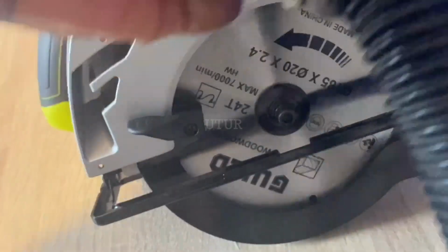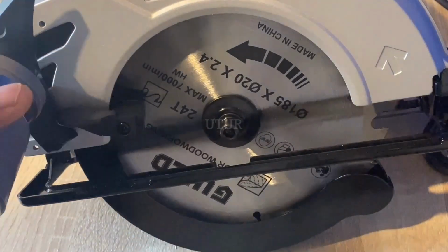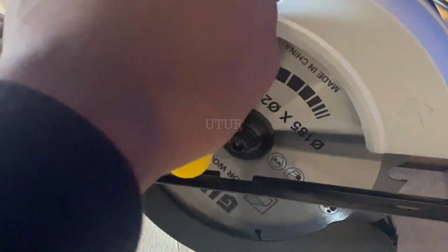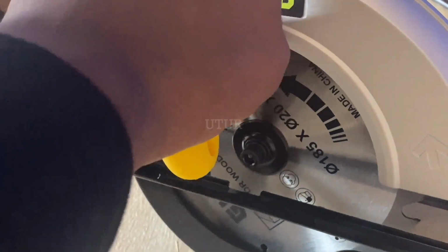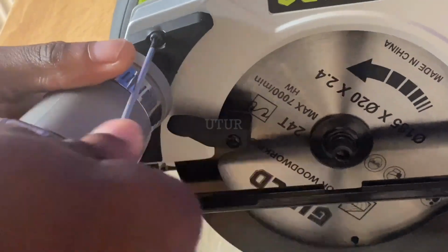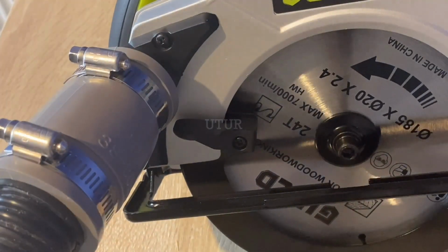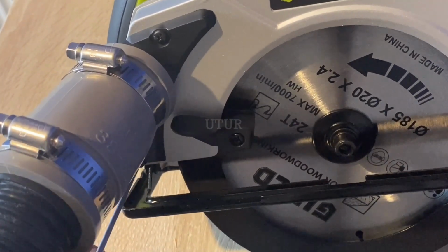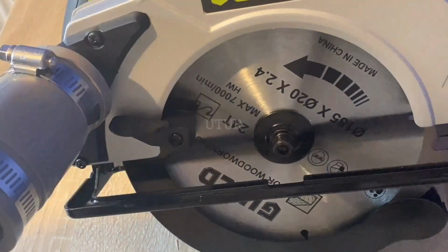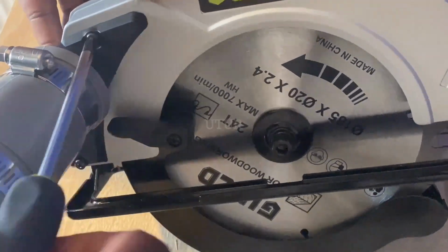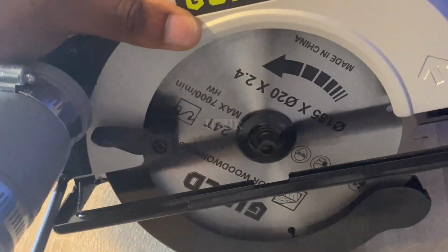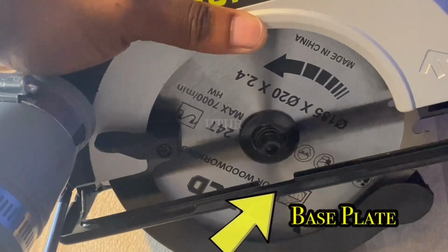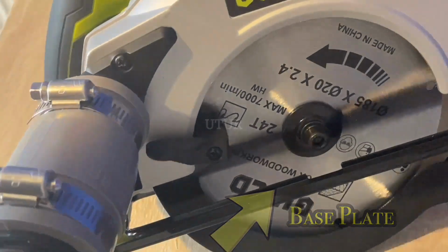Once the hose and the vacuum adapter have been adequately secured onto the coupling, then you install the vacuum adapter with two screws onto the circular saw, just like I've done here, onto the fixed guard. So we have fastened the vacuum adapter onto the dust extraction outlet, onto the latches, onto the fixed guard with two screws. And prior to this, connected directly a suitable vacuum hose to the adapter.